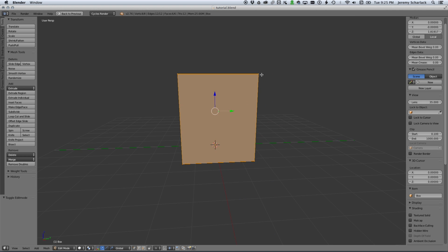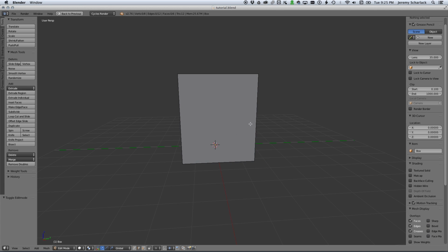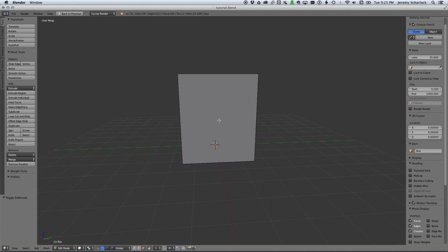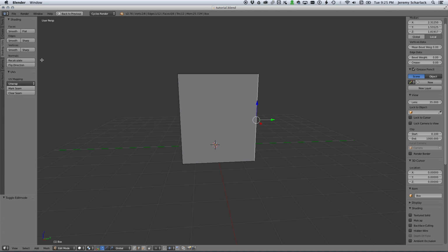And then right now we can select what's called the points or the vertices. But we want to be able to select the edge so we can make a seam out of it. So go down to edge select. This, by the way, is face select, the third select option. But we want edge select. Let's go to edge select, and then you want to go into Shading, UVs, as I said, UV, and you say Mark Seam. So that marks the seam.